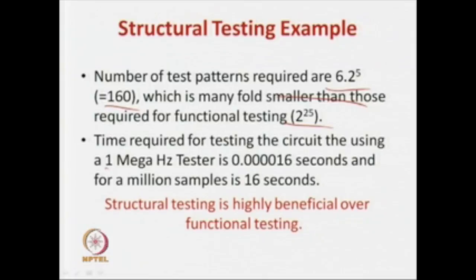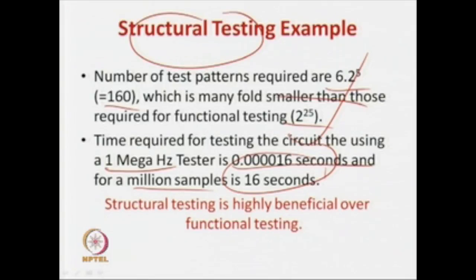So, if we are using the same tester, which is a 1 megahertz tester, then the time required for testing is only this many seconds, and if you have to test a million samples, then you require only 16 seconds. So, structural testing is what has to be adopted, and that is very good, but the penalties of extra pins and extra muxes, somehow we have to take these things into account.